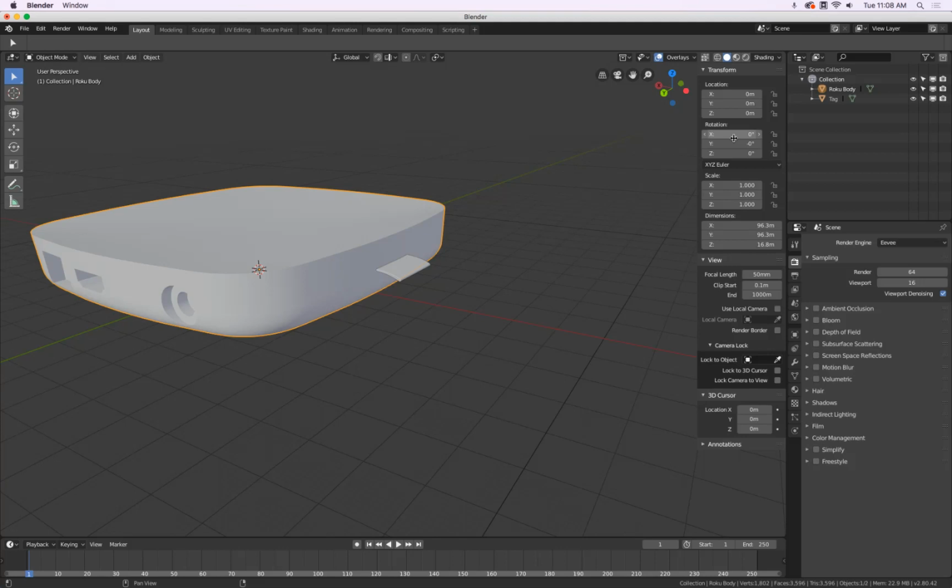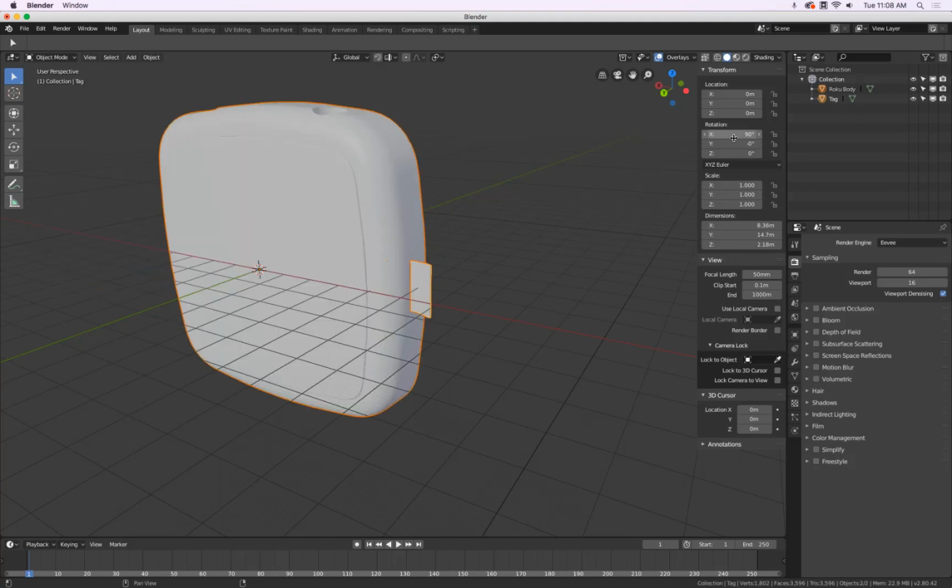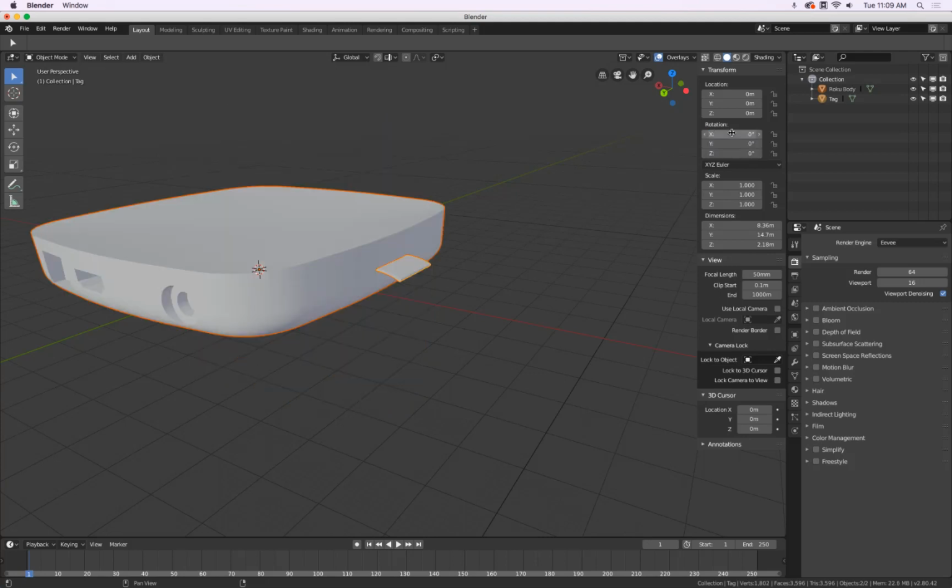And in case you want to do both at the same time, you have to hold the Alt key, or Mac also calls this the Option key. So hold the key, click and drag X to Z, release the mouse button, release the Alt key, type in 0, enter, and now you see it adjusted everything at the same time in both objects.